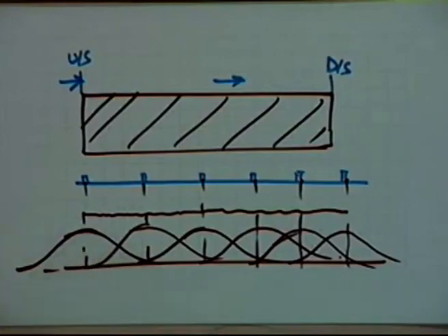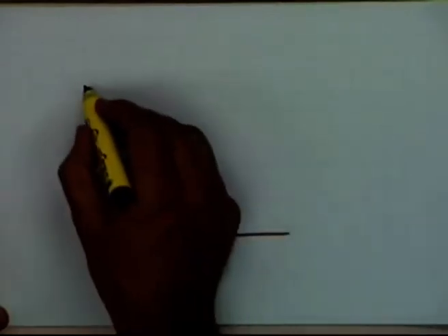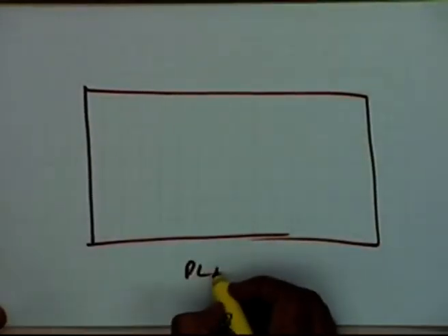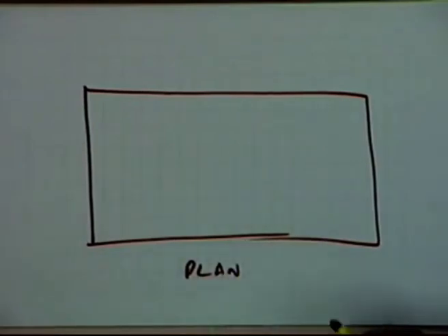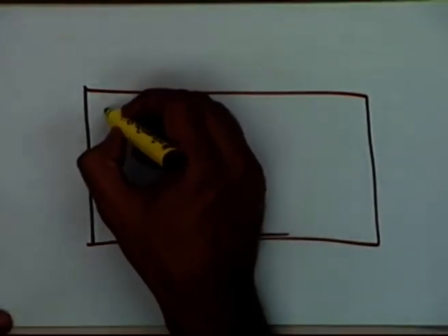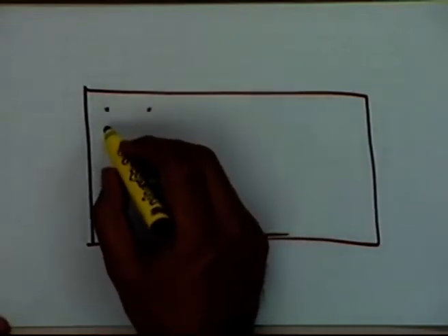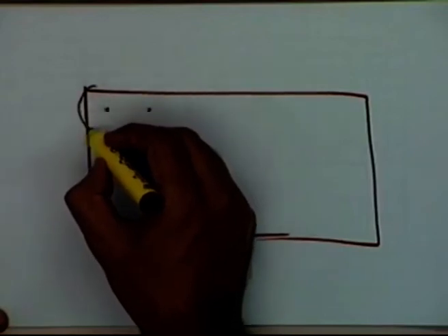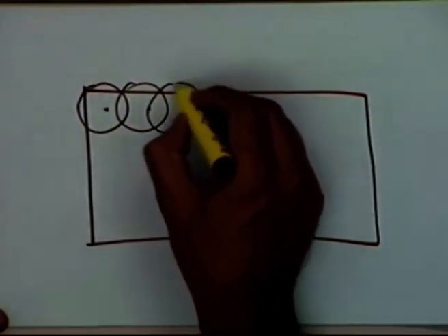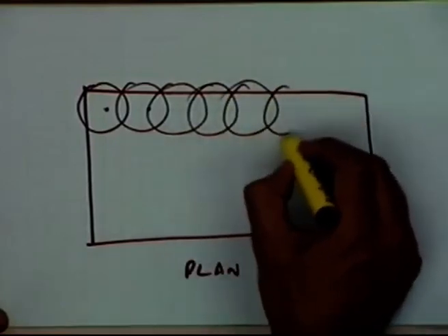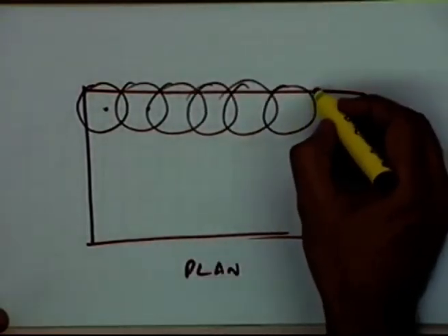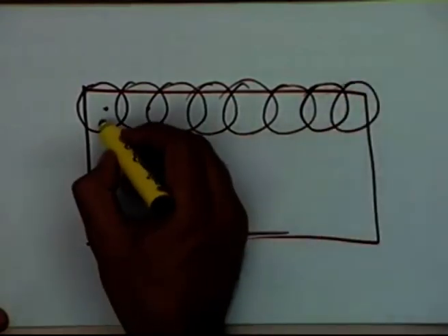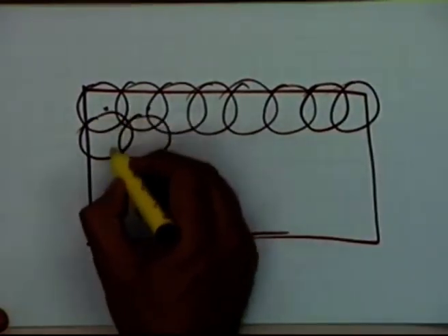Similarly, this is one overlap in one direction. Let me put the whole thing in plan. If I show the field in plan, now I might locate the sprinkler heads in such a way that this overlap, which will give me a good, uniform distribution, will have to be considered in both the directions.